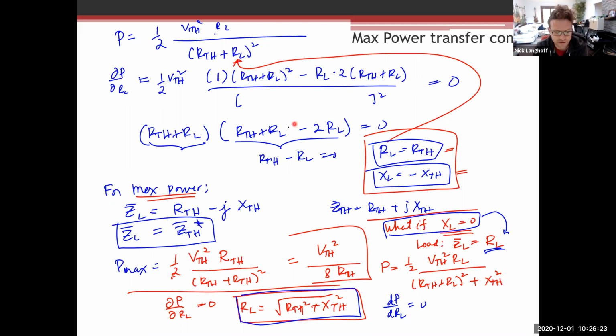And essentially what they say, the punchline, if you will, is that to maximize power the load impedance should again be set to the Thevenin, the load resistance, sorry, the real part, should be identical to the Thevenin resistance. And that's the same as it was for when we were just looking at maximum power with just resistive circuits, right?